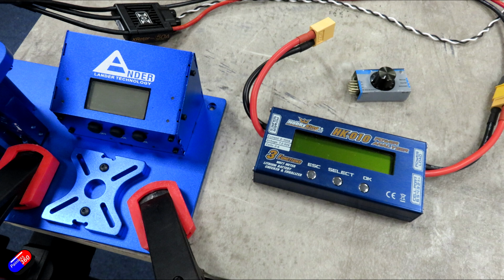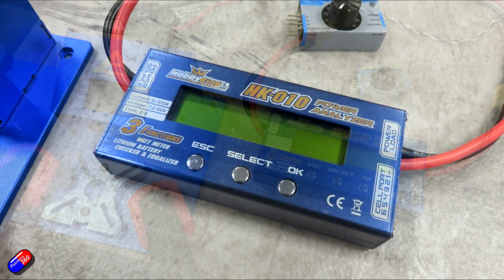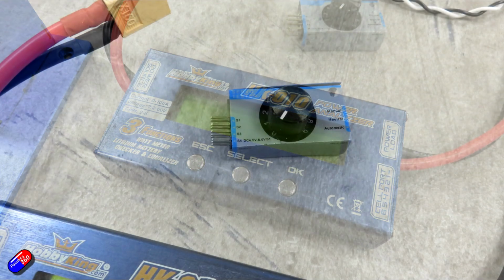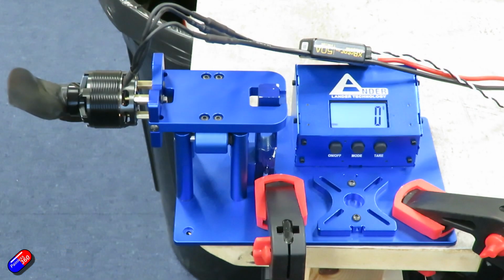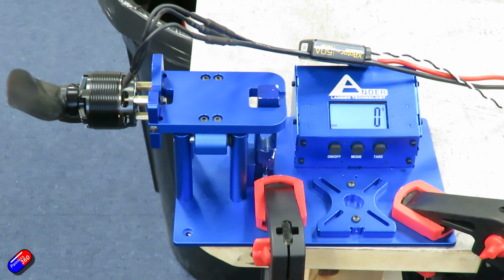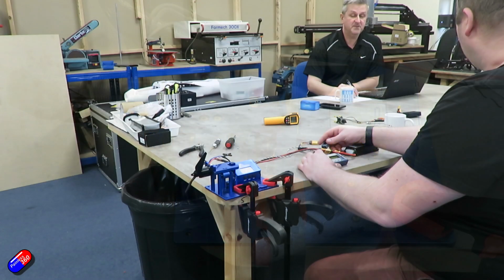So to actually do the testing, what we did was bolt it down. I'm using this thrust measuring device. This is actually one that I got from Banggood. I'll put a link down below. Occasionally they struggle to keep these in stock. And then what I'm using is a watt meter, and we're using a servo checker to provide the power. And again, the ESC has been calibrated, so when we're 100%, it is 100%, and it's going to be consistent across all the tests too.